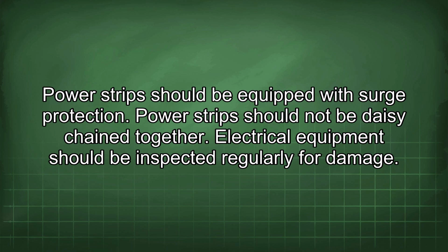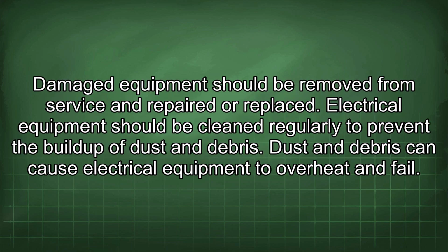Electrical equipment should be inspected regularly for damage. Damaged equipment should be removed from service and repaired or replaced. Electrical equipment should be cleaned regularly to prevent the buildup of dust and debris. Dust and debris can cause electrical equipment to overheat and fail.